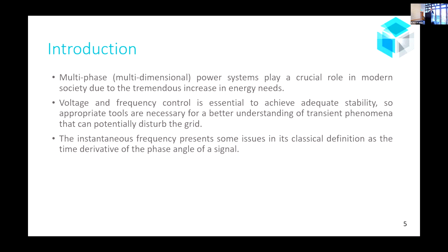We also need a better understanding of the underlying meaning of some parameters. This is the case for the instantaneous frequency. This is a disputed and controversial concept. So how can the repetition of something be considered at a specific time? For this, some assumptions are made, like considering the signal a sinusoidal one, and applying quadrature methods to extract the instantaneous phase and amplitude, like, for example, the Hilbert transform does.